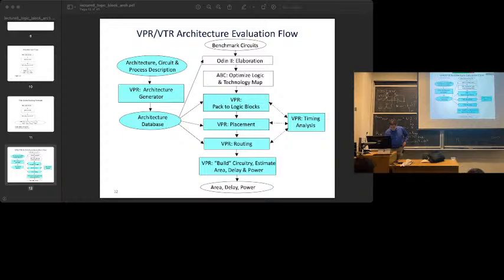Okay, after that, we pack into logic blocks. A logic block is more than just a single lookup table. It has some local interconnect. We figure out what's legal and what's desirable to put in a logic block. Then we have to choose where to put all those blocks, including RAM blocks and DSP blocks. We might have 10,000 blocks and 20,000 locations. Where do we put every one of these? And then route them: pick which wires we are going to use, which switches we are going to use. All of these stages, packing, placement, and routing, strongly influence how fast the circuit is.